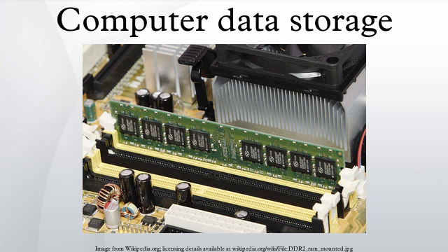Optical storage, the typical optical disc, stores information in deformities on the surface of a circular disc and reads this information by illuminating the surface with a laser diode and observing the reflection. Optical disc storage is non-volatile. The deformities may be permanent, formed once, or reversible. The following forms are currently in common use: CD, CD-ROM, DVD, BD-ROM, read-only storage, used for mass distribution of digital information; CD-R, DVD-R, DVD+R, BD-R, write-once storage, used for tertiary and offline storage; CD-RW, DVD-RW, DVD+RW, DVD-RAM, BD-RE, slow write, fast read storage, used for tertiary and offline storage.